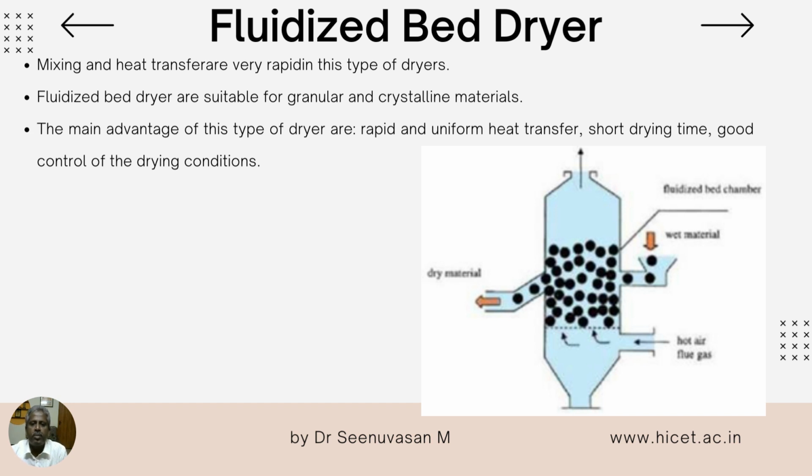If fine particles are present, either from the feed or from particle leakage in the fluidized bed, there may be considerable solid carryover with the exit gas, and bag filters are needed for fines recovery. The main advantages of this type of dryer are rapid and uniform heat transfer, short drying time, and good control of the drying conditions. In the case of a rectangular fluidized bed dryer, separate fluidized compartments are provided through which the solid moves in sequence from inlet to outlet.